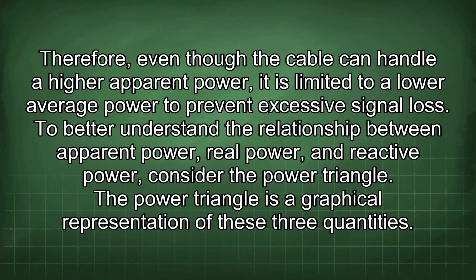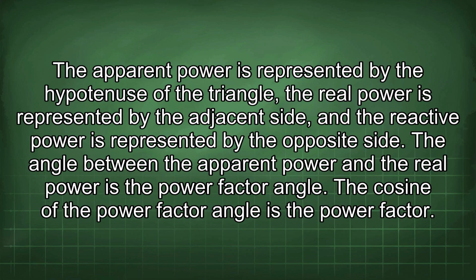To better understand the relationship between apparent power, real power, and reactive power, consider the power triangle. The power triangle is a graphical representation of these three quantities. The apparent power is represented by the hypotenuse of the triangle, the real power is represented by the adjacent side, and the reactive power is represented by the opposite side. The angle between the apparent power and the real power is the power factor angle.